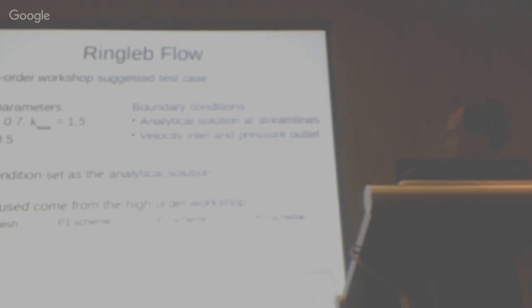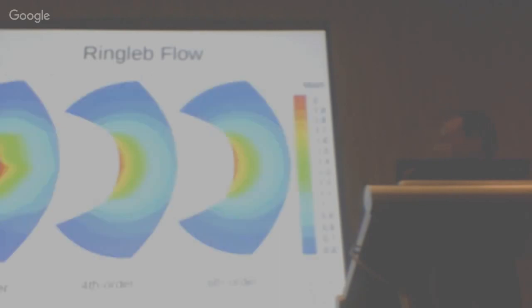For this one, we used several different types of meshes and different levels of refinement. What I'm showing here, the initial mesh is just half of the domain, and it's really coarse like that. And these several other ones are simply visualizations of the spectral difference elements. This is not part of the actual visualization process. The solver has the various solution and flux points that I simply plot here to aid in the visualization step. It's a Mach contour plot.